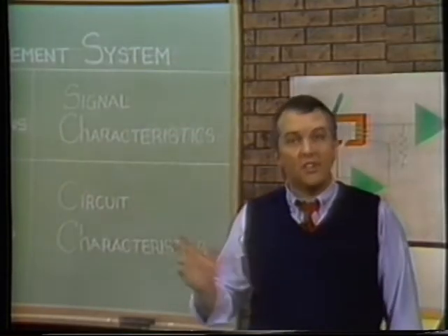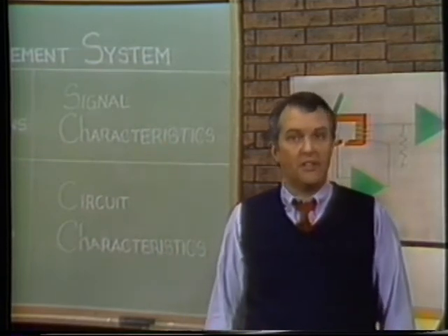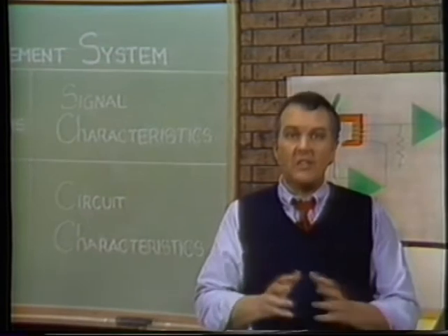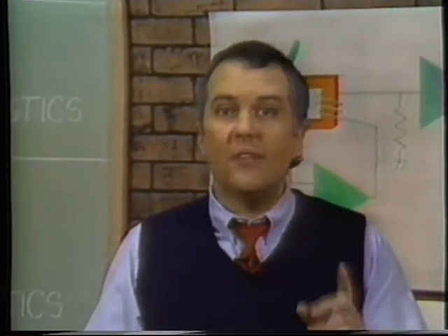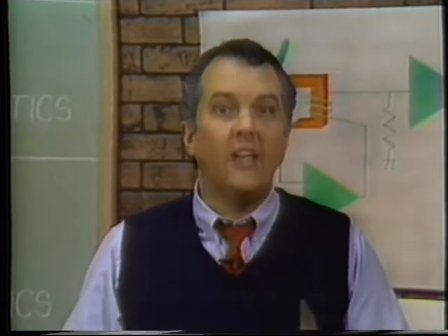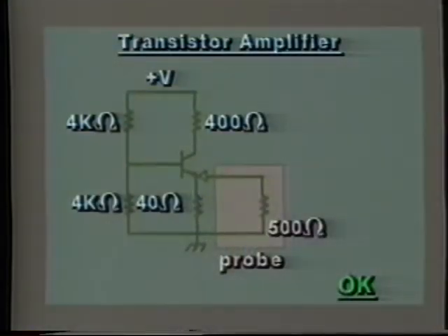Remember that I said the circuit under test and the signal characteristics play a big part in probe selection. We have to look at the impedance of the probing point. It's generally okay to use a low Z probe if the source impedance of the test point is 1/10 the R in of the probe. Otherwise, we'll change the circuit impedance by more than 10% when we attach the probe. Remember, to accurately use a 500 ohm probe, look for a test point impedance of 50 ohms or less.